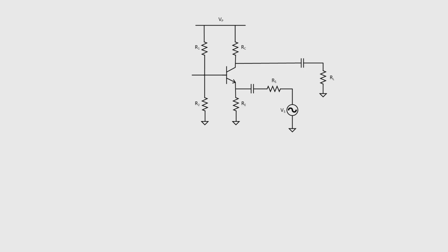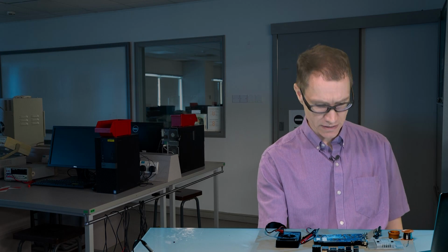So you might be wondering, why would you want to do that? What's the advantage? Isn't it just like the common emitter configuration, but without the benefits of the high input impedance? That's what we're going to look at here with this example. If we merely take the source and instead of putting it here at the base, we put it over here at the emitter, we wind up with what I call a bad common base design. In a moment, I'll show how we can make it not bad, but let's start off by listing all of the reasons why this is a bad design.